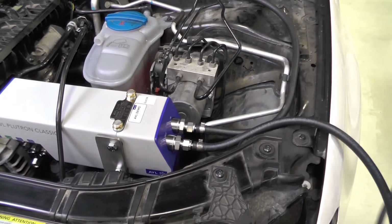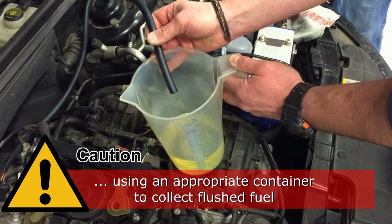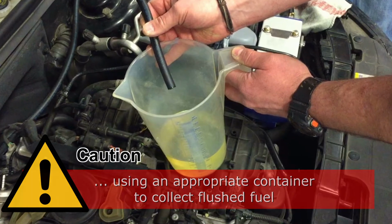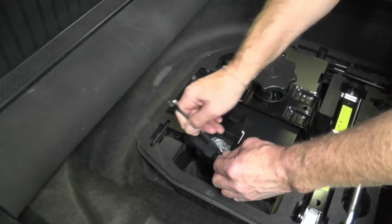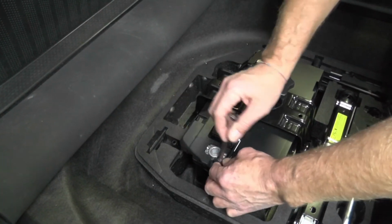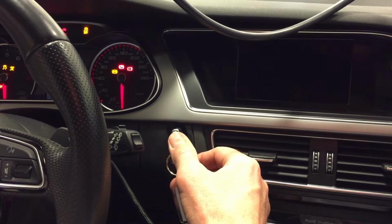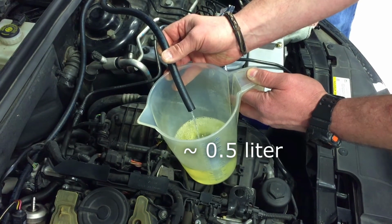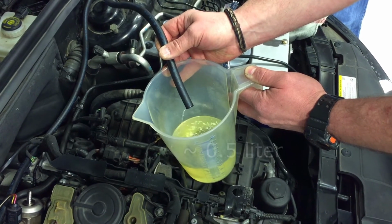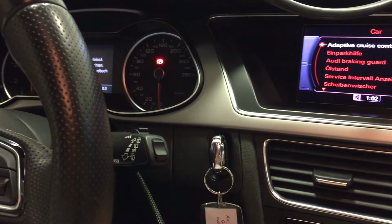Before we connect this second hose to the pump inlet, however, we should flush some fuel through the hoses and the meter. Make sure the hose end leads into a bucket or other container to collect flush fuel before you reconnect the battery, as the fuel pump may start pumping as soon as you close the battery contact. Ignition, or even operate the electric starter of the vehicle in order to flush roughly half a liter of fuel through the lines into the bucket. Then power off the fuel supply again.